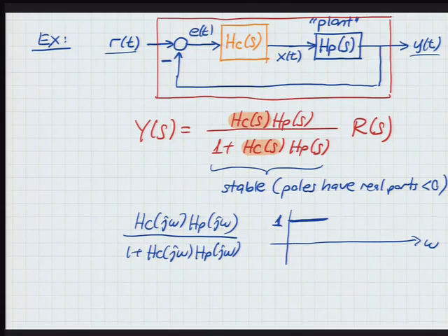Typically, we can make this happen for low frequencies. But if R is moving like crazy, it's very hard to make Y follow it exactly, right? So what happens typically, I'm just giving you a preview without any proofs or derivations now, is that inevitably the frequency response will start rolling off. It just comes from the fact that the plant itself will probably have a roll-off. It will not transmit high frequencies. Therefore, we can't expect that from the closed-loop system either. So one of the design criteria is to make this range of 1 last for as long as possible.